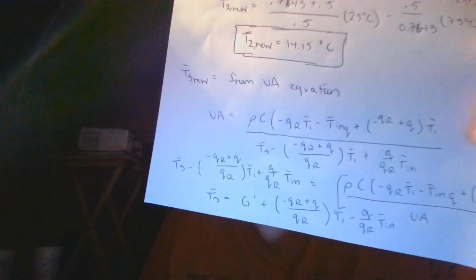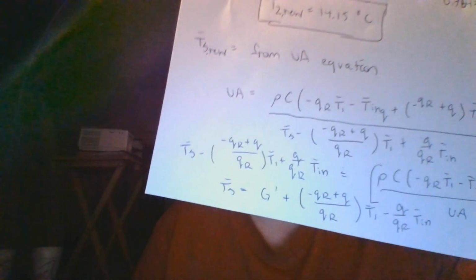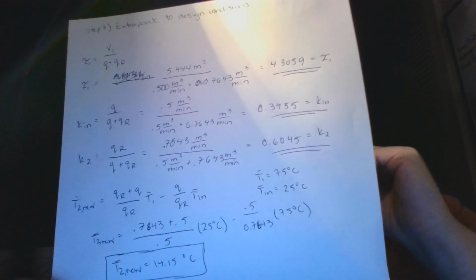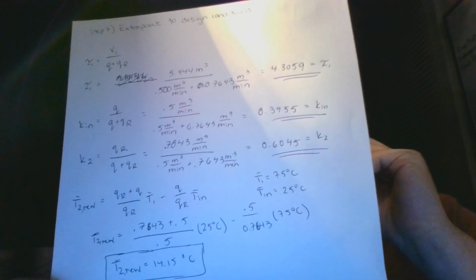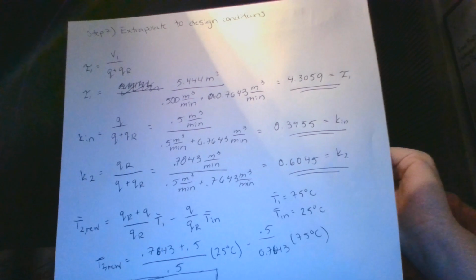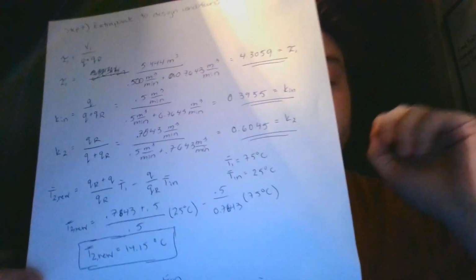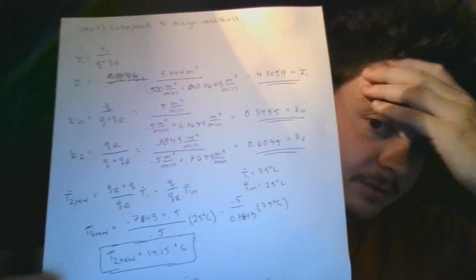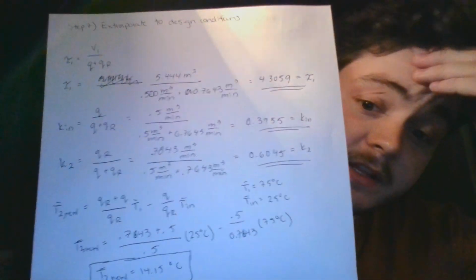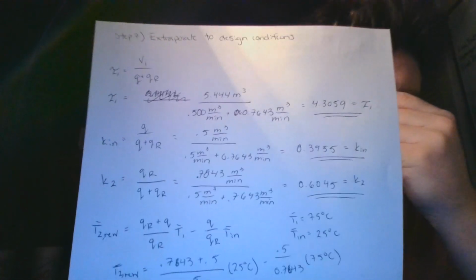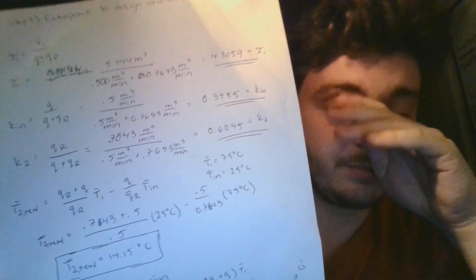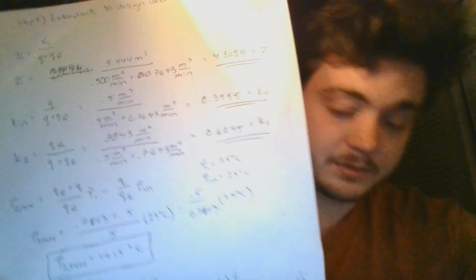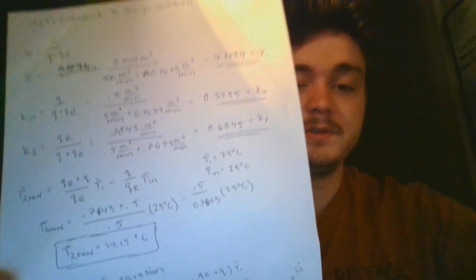This is very important for understanding the accuracy of the model, as well as the ability for the model to respond quickly to different variables or changes inside of the vessel. This was done by solving for a characteristic equation that was modeled with the gains as well as the open loop Laplace transform that would then be set equal to 0.